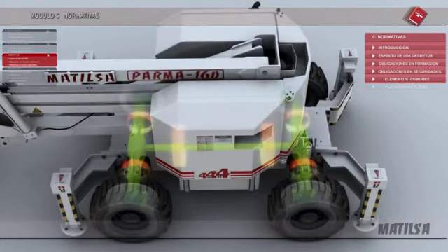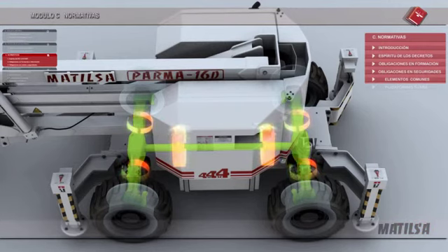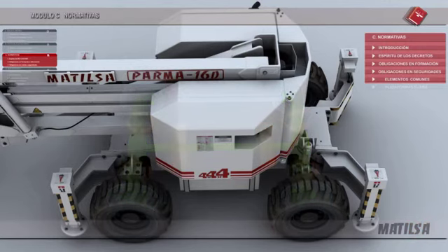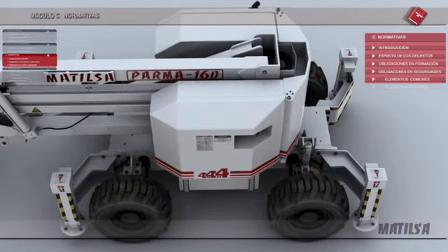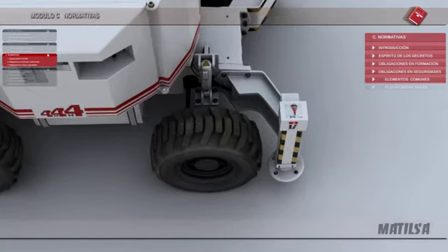By means of a differential group, or two, if the machine is 4x4. For machines with differential groups, which normally carry the brakes with them, the procedure normally is to hit a device which projects out through the axle to unblock the brake, although the best thing is to look at the manufacturer's instruction manual.